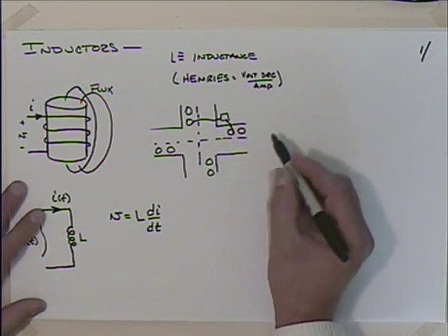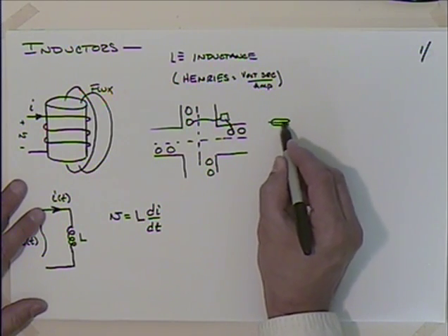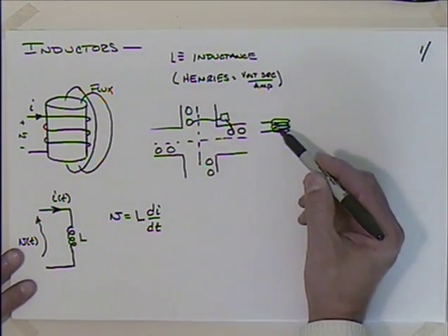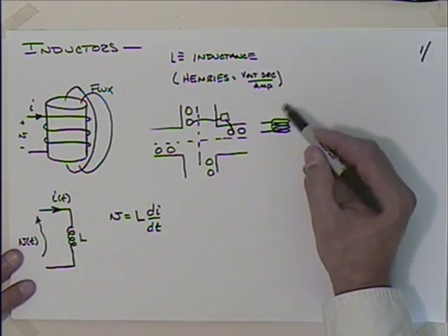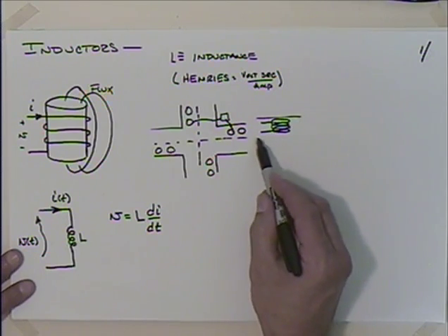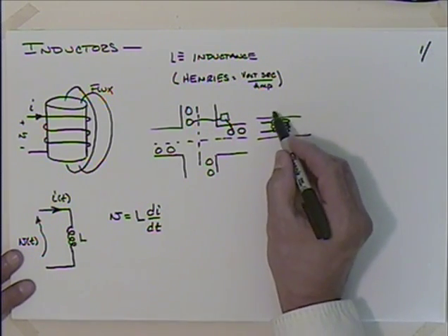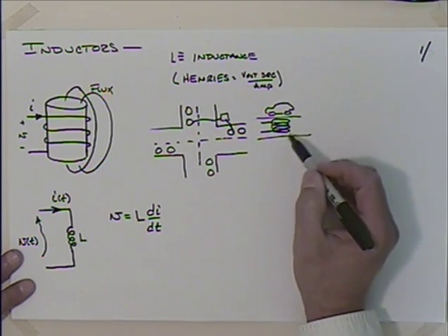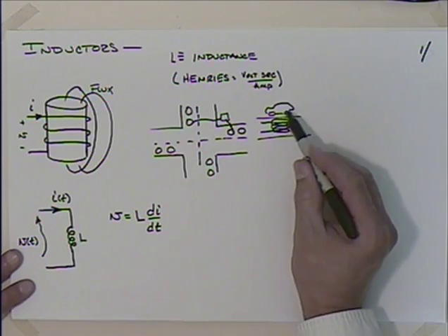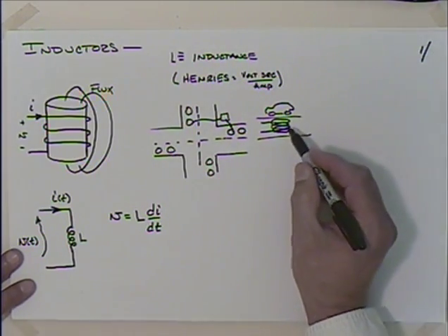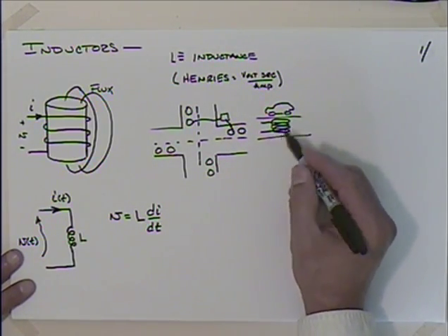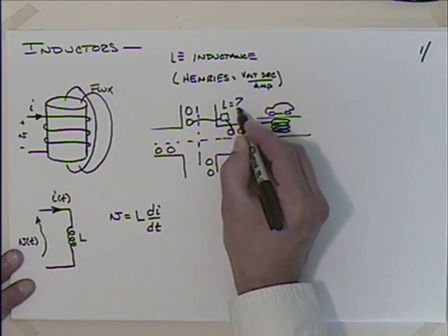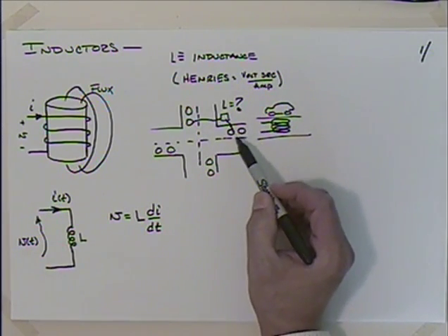When you think about this coil, when there's no car there, the core is going to be asphalt and air. This is embedded in the asphalt. When a car drives over this, the core is now asphalt, air, and car, or iron. The car's probably got some iron in it, so the inductance changes. What this control box is doing is querying what the inductance is, so that you can figure out where the car is.